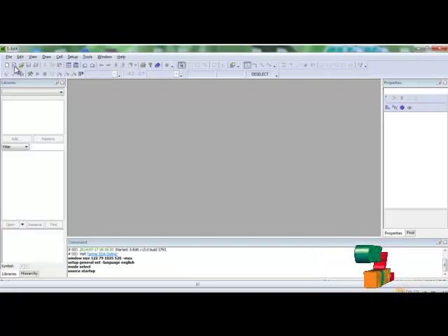By clicking this, we can start a new project. To start every new project, we have to open a new cell. By clicking the cell, we can design a new circuit. In the cell, we can include a lot of libraries which consist of transistors, CMOS transistors, resistors, capacitors, such as general devices.